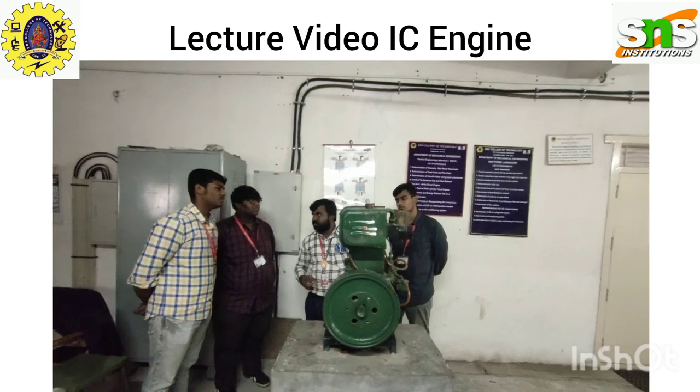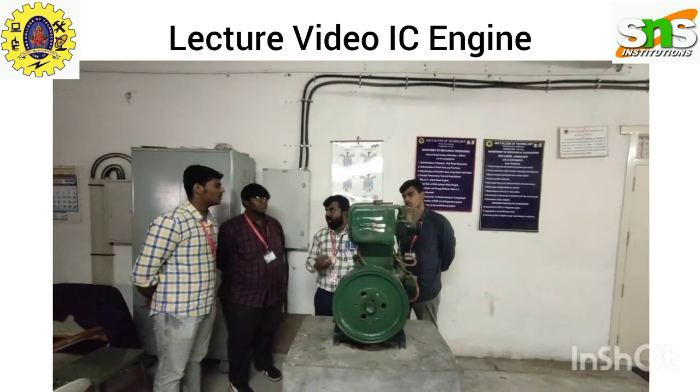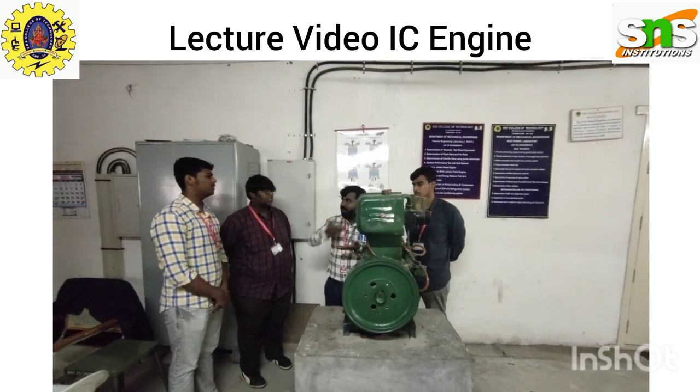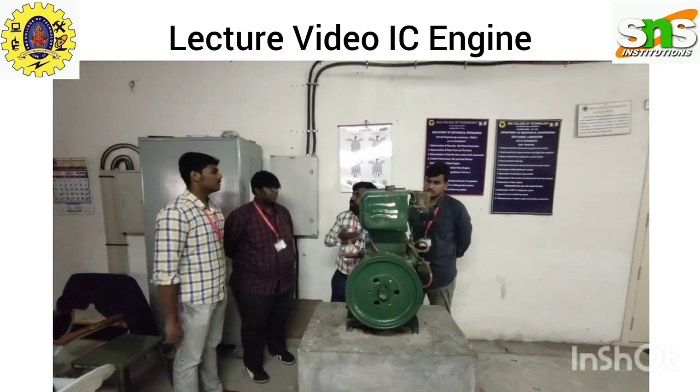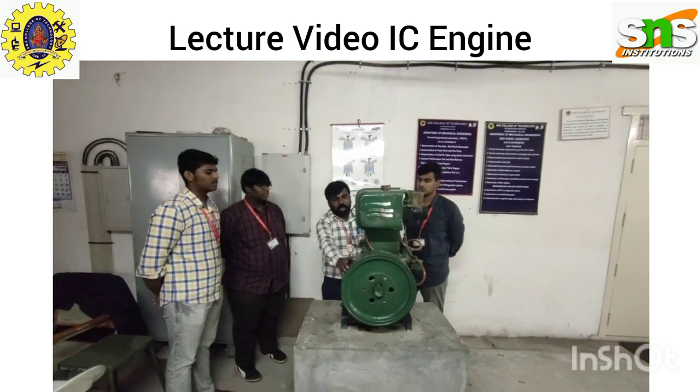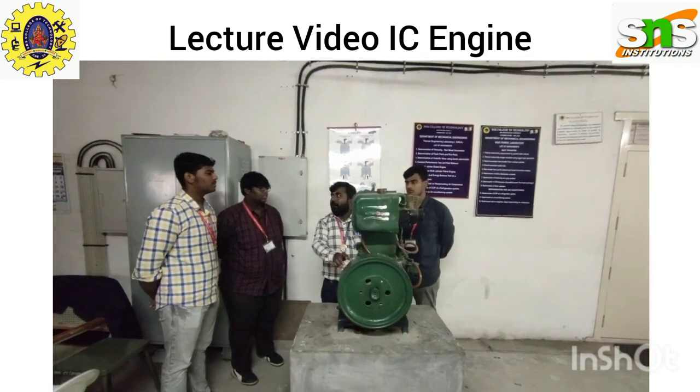during the suction stroke only air is sucked from the environment. From top dead center to bottom dead center the piston moves. This is called the suction stroke. Again the piston moves from bottom dead center to top dead center. This is called the compression stroke.